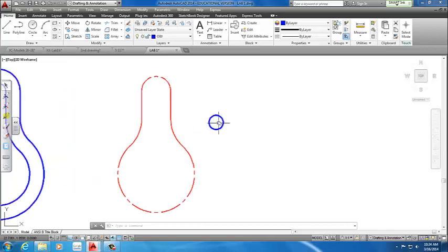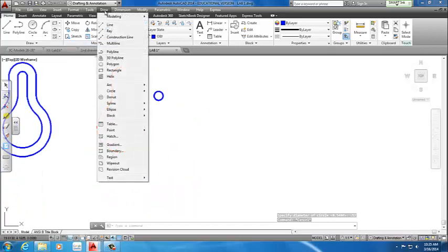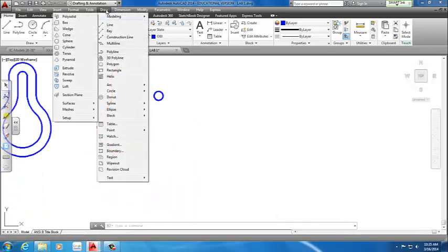Next step will be to use the revolve command. If you are not in 3D modeling or 3D basics, it's alright. Well, you don't have to be because this is pretty simple. We can just go to the draw tab, modeling, and there is a revolve option. Actually, I'm sorry, this is a mistake of mine. Sweep command, that's the one we want to work.